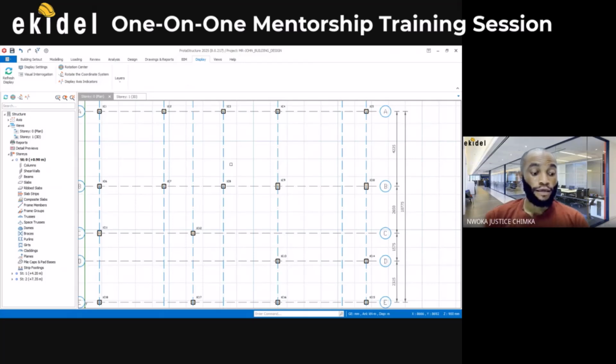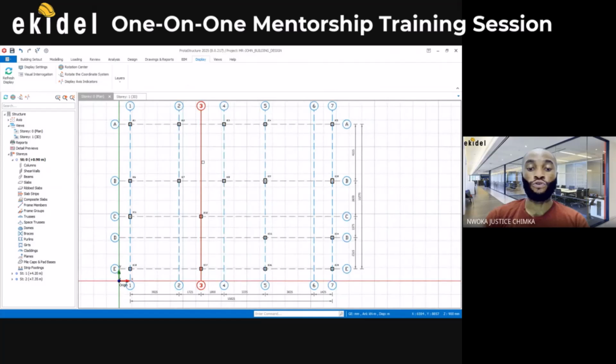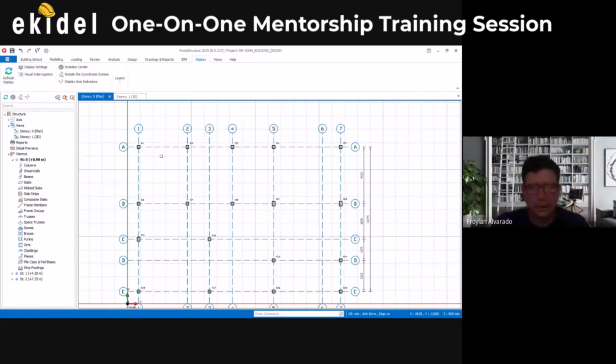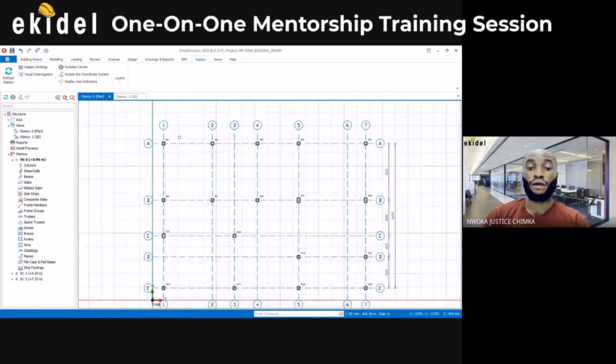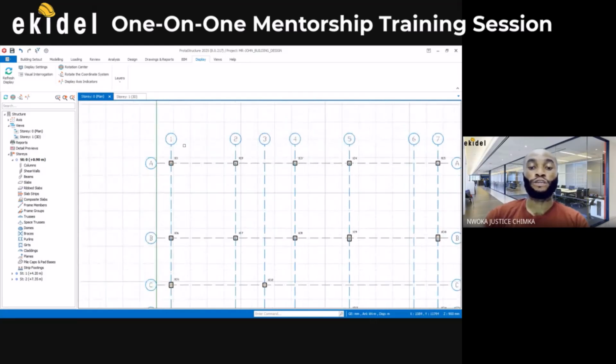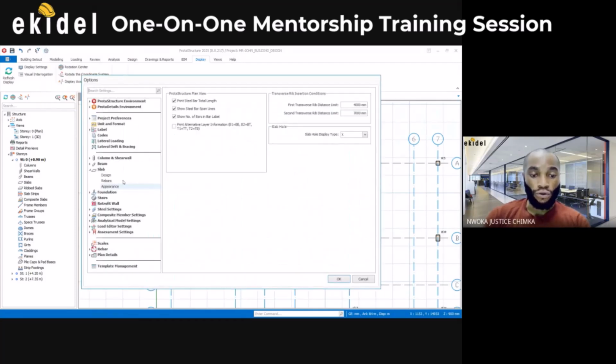Now, you say that in your country you use more of mini piles, right? Yes. Okay, so with that we will start with a pile foundation. To begin a pile foundation, you have to make some settings first. It's still under setting center here. I'll click on setting center, and then I'll click on foundation.